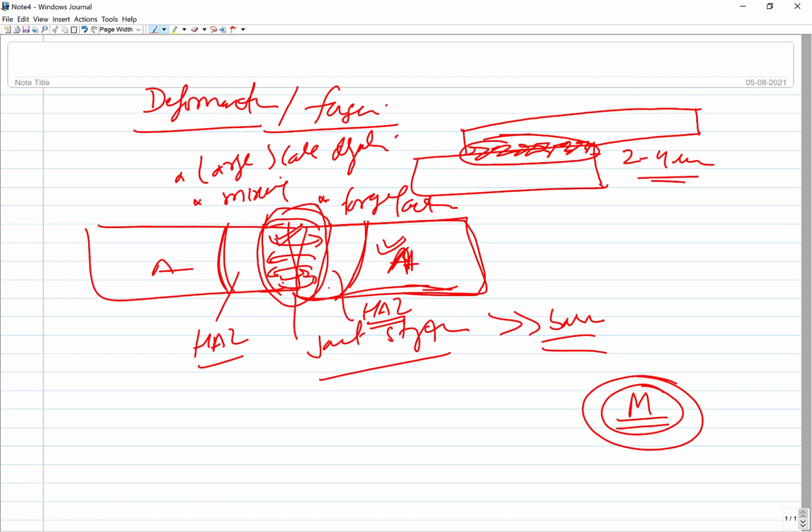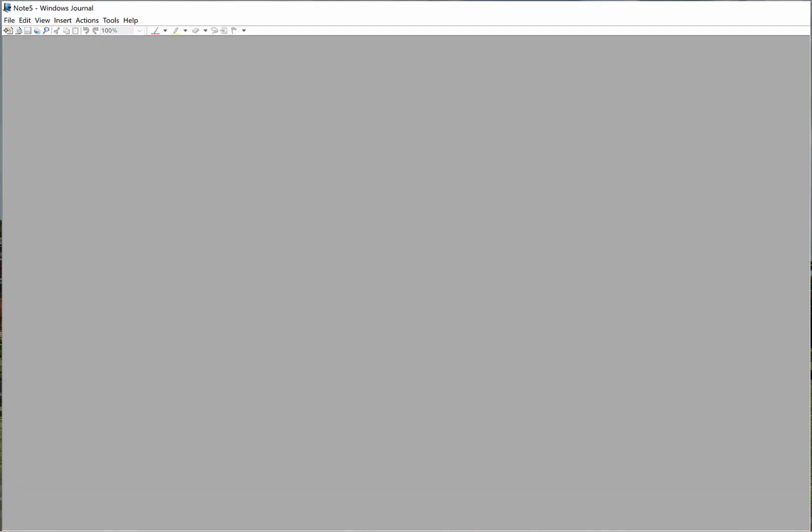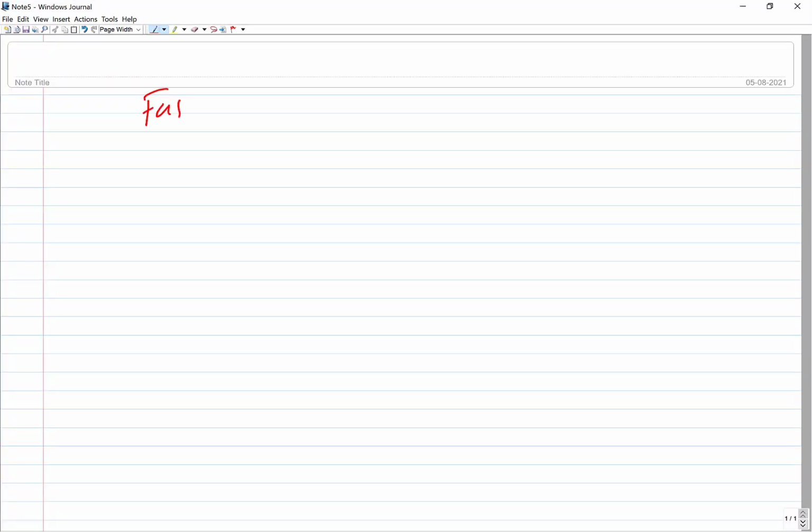The weld nugget area is deformed, and the heat affected zone area will be experiencing changes due to the frictional heat or the deformational heat which is introduced in the base metal during the weld joining itself.